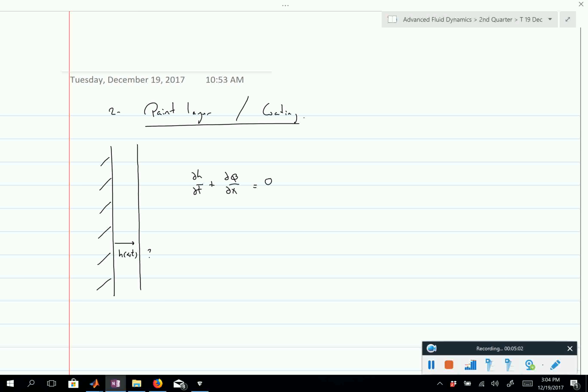And then we have the x and the y momentum equation. Now either you flip all of your axes, right? But if you want, at this point I would encourage you to be a bit flexible, and I would pick this, right? Does that make sense to you? Because then we just essentially keep on saying the x direction is the flow direction, and the y direction is the direction across the flow. So that would be a choice which would help you if you directly flip your axis such that you're using the same equations that you're used to. Then it's going to be easier.